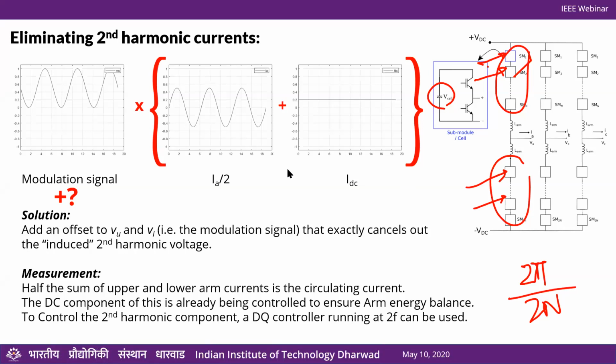Next one, practical application of MMCs in general. HVDC, that was the most popular and most sought after use for MMCs. I covered that in the first few minutes of my talk. Then, since MMC has a large number of series switches, it could have appreciable conduction loss. Yes, absolutely. It has much more loss.